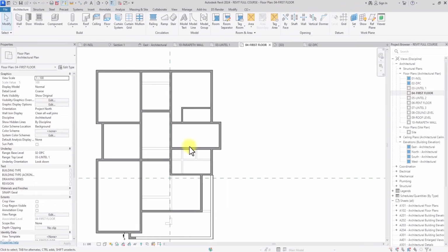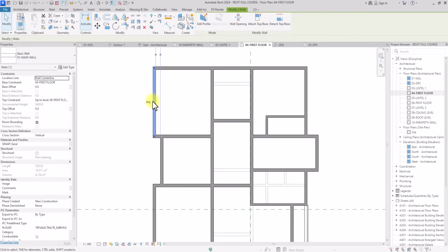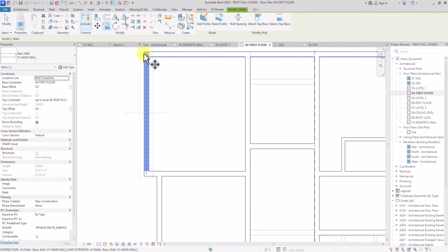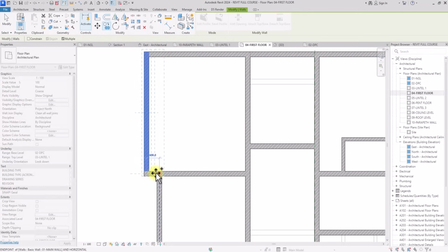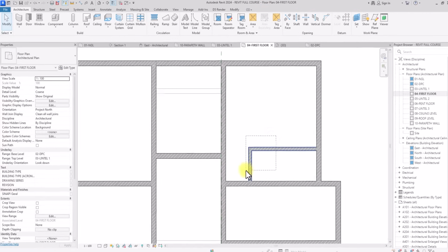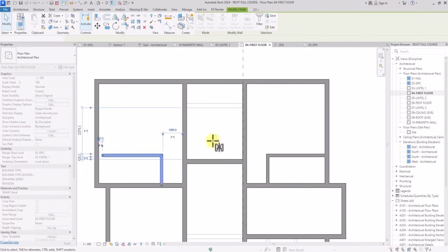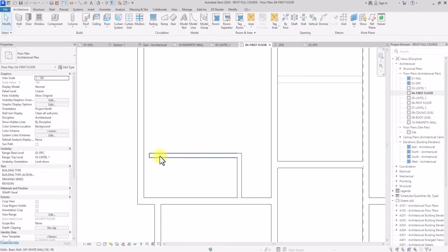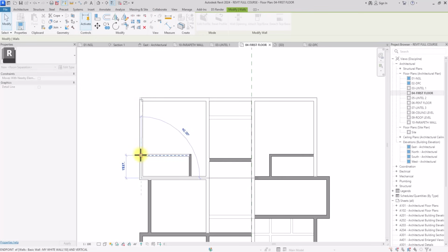I'm going to try and create some other small mini balconies for these respective bedrooms. So for this one now, I'm just going to click on this wall. I'm going to copy it and drag it and align it to this other wall. Of course, I remember we are going to create a convenience here. We are just going to balance it. So I'm going to select this and click on mirror, select the center of this lobby and just select this here. All right, so now I'm just going to drag this here and I'm going to click on this wall and drag it to this point.